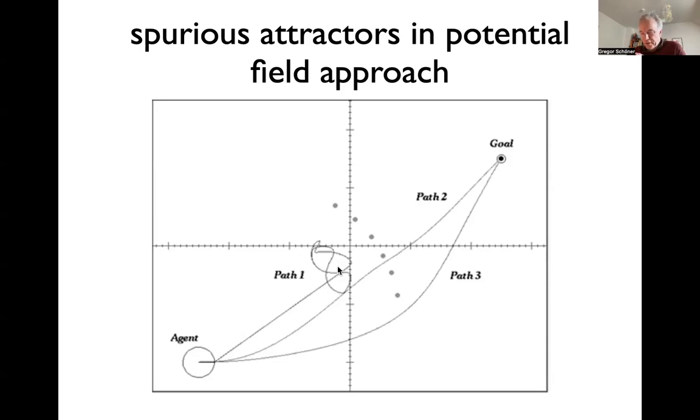You can think of this potential field as a landscape, and there's a big valley that leads to the target, and then you have some small hills, which can create something like a mountain lake right in front of these hills as part of the big valley. And that is actually somewhat generic, and there is even some mathematical proof about how likely that is, and it's very common. In fact, potential field approaches very generally have this problem.